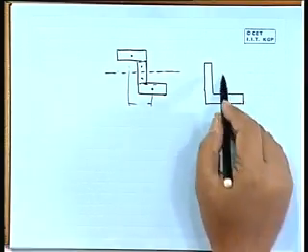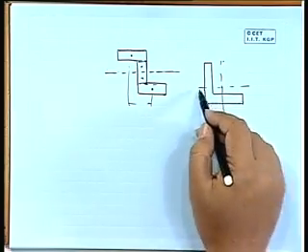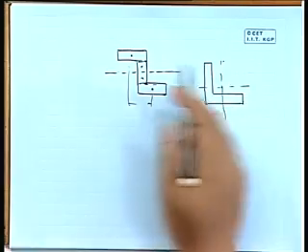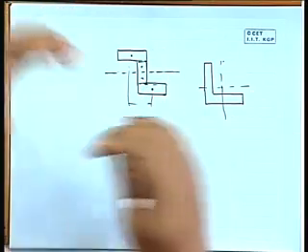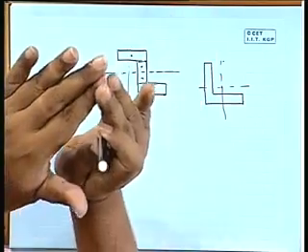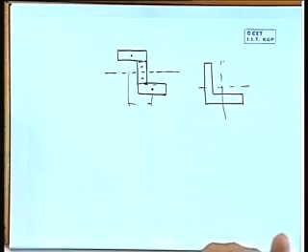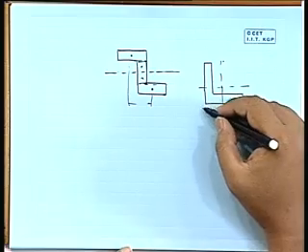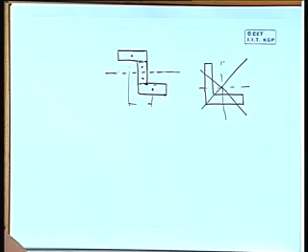say the centroid is somewhere here. Now about this axis, it is not symmetrical. So if there is one angle and there is a load, we can't do the analysis directly. Say one of the legs of this angle is horizontal, another leg is vertical, and the load is acting vertically downward. So straightway if we calculate the moment, and from here if we calculate My by I, it will not work. Now here what we have to do, we have to take one axis system like this, right.